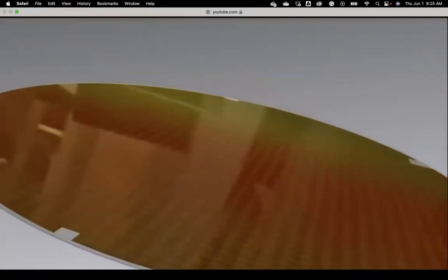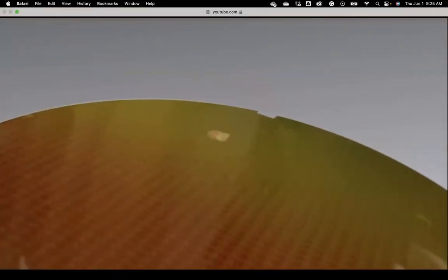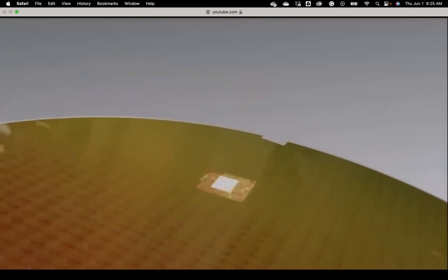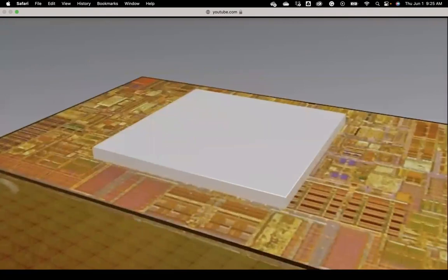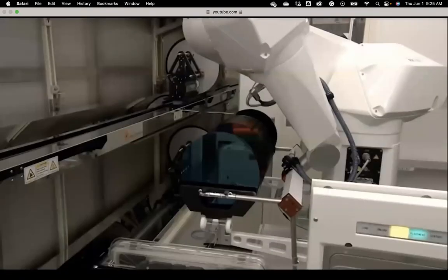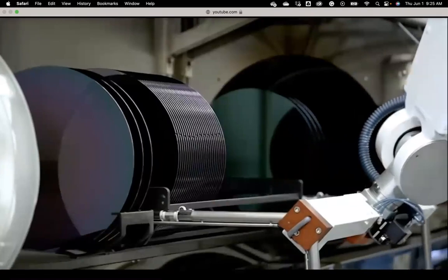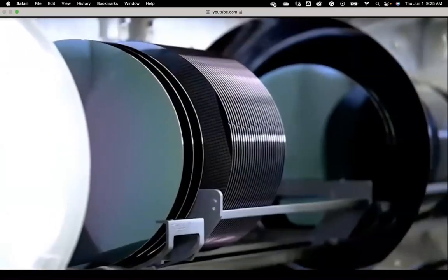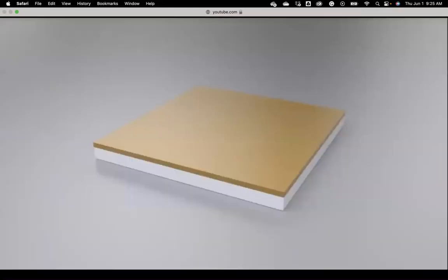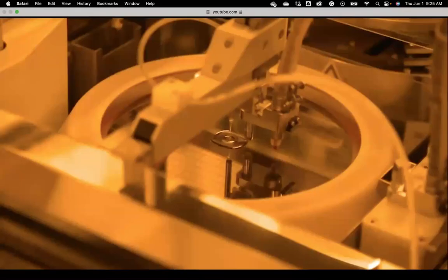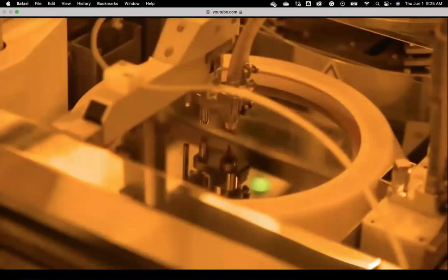Chips are built on a base wafer cut from a silicon boule. Depending on their size, several dozen or several thousand chips can be fabricated on one wafer. First of all, the surface of the wafer is oxidized in a high-temperature furnace operating at approximately 1,000 degrees Celsius to create a non-conductive layer. Then a photoresist material is uniformly distributed on this non-conductive layer using centrifugal force. This coating process creates a light-sensitive layer.